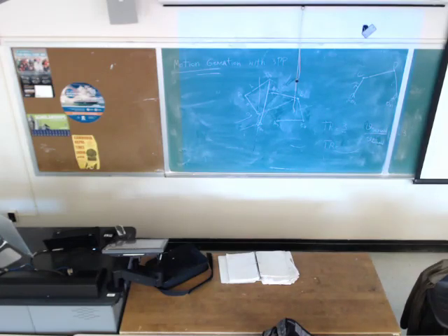So let's go back to this crank rocker mechanism. When this crank is moving from this position to this position, the rocker is moving from B1 to B2. On the backward motion, it's moving from A2 to A1, and from B2 to B1. As you see, this angle is 180 degrees for forward, and also 180 degrees for backward.